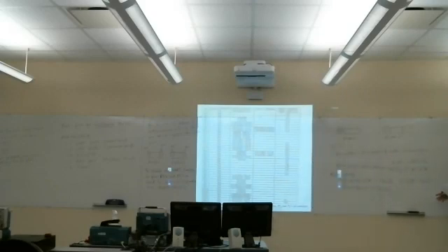Okay, so this is the first step. Set the function of the pin that you're going to use. And by default, most of them are in the general purpose IO state already. So we don't really have to change the purpose if that's what we're using them for. It's not bad practice to go ahead and set them anyway appropriately in some initialization portion of your code, before you get into the loop.